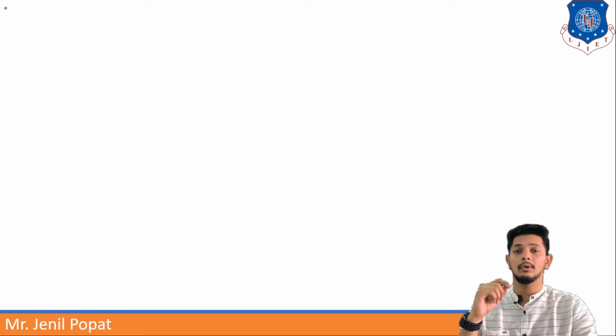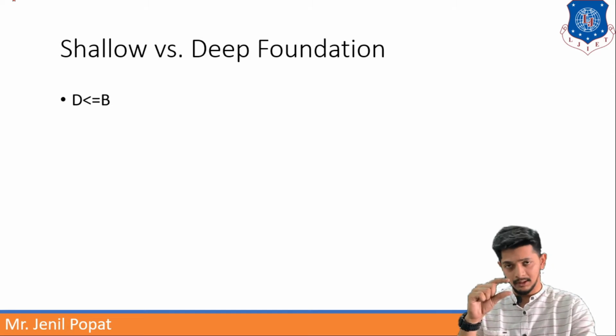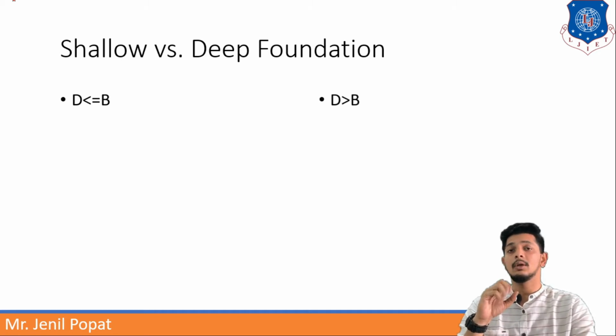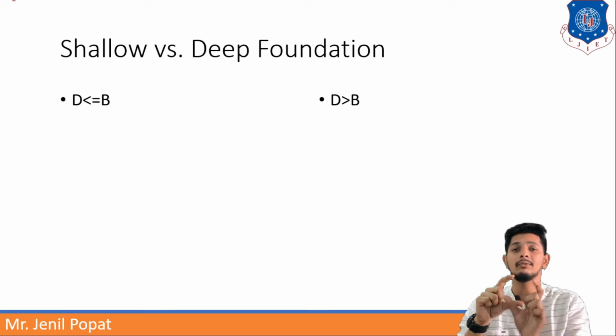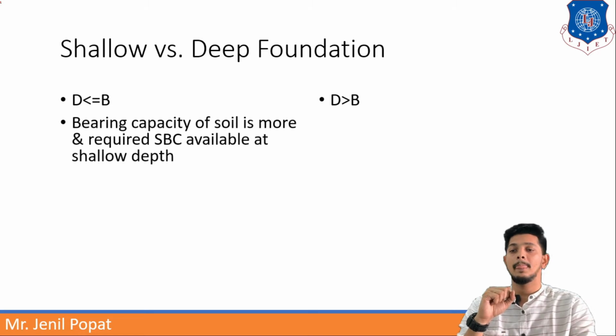Let us move forward. Shallow versus deep foundation. So let us understand shallow foundation and deep foundation. When the depth of the foundation is less than or equal to its breadth, it is known as a shallow foundation. When the depth of the foundation is greater than the width of the foundation, it is known as a deep foundation.